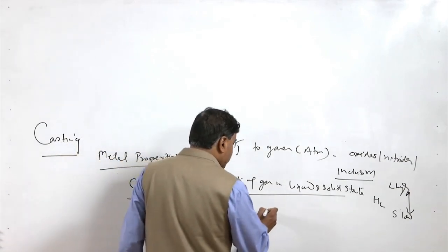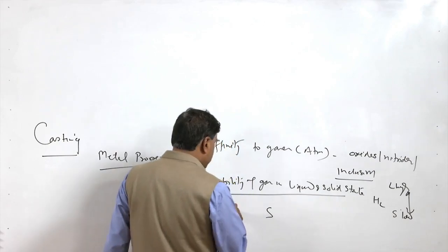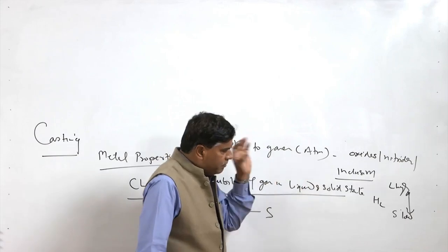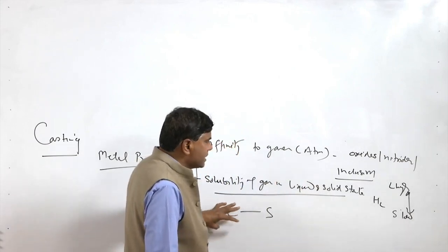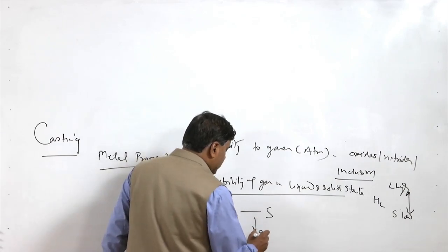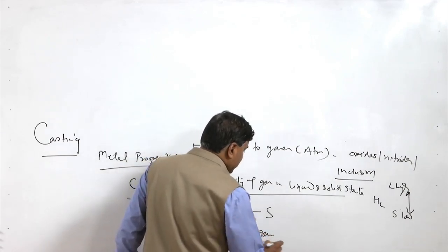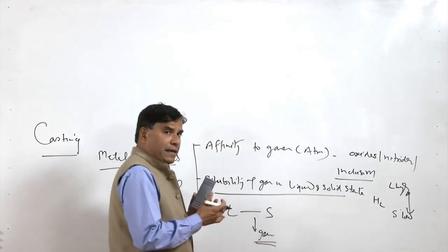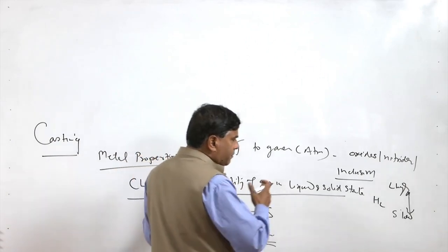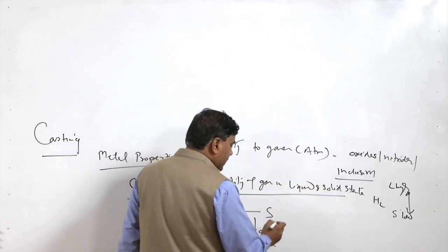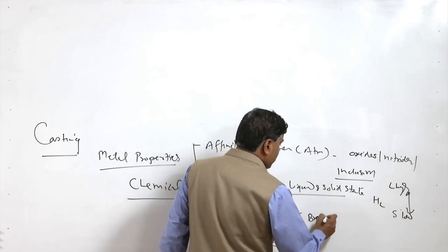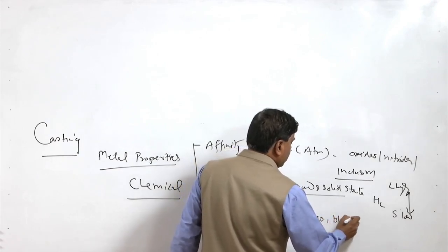We know that during solidification, liquid to solid state transformation takes place. Since the solubility of the gases in the liquid state is high, in the course of solidification these gases will be released. These gases must get enough opportunity to escape from the molten metal during casting, and if that does not happen, they will be present in the form of pores or blowholes.